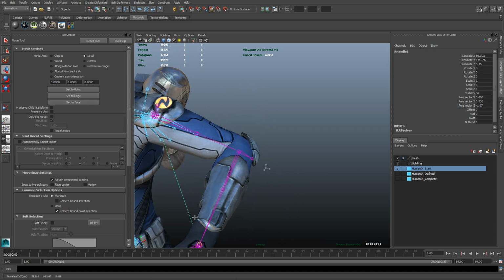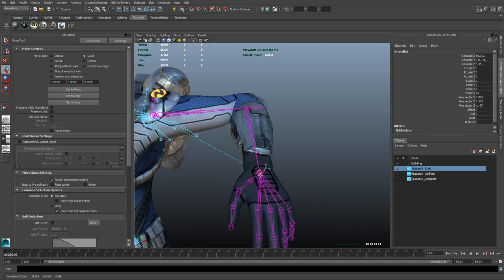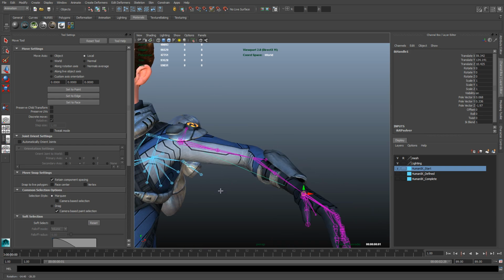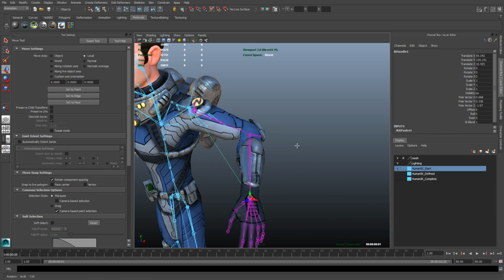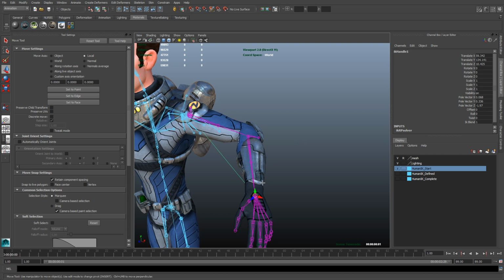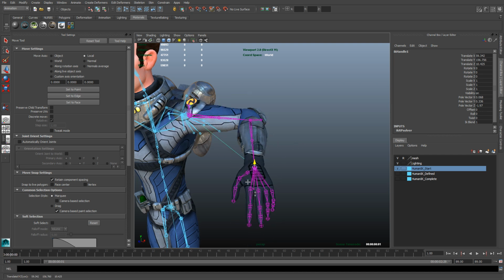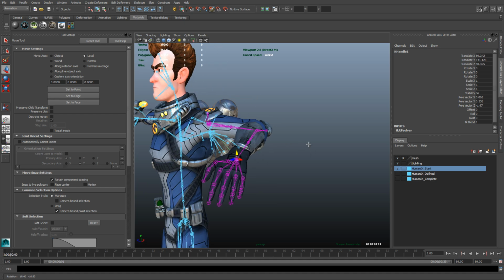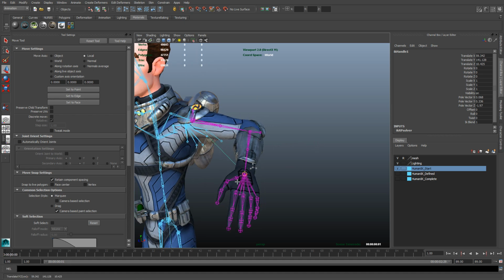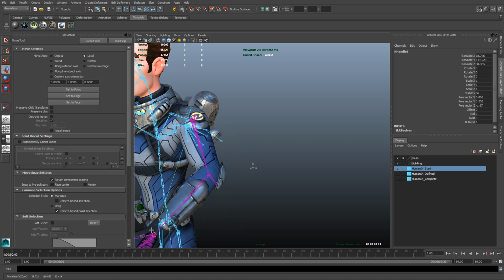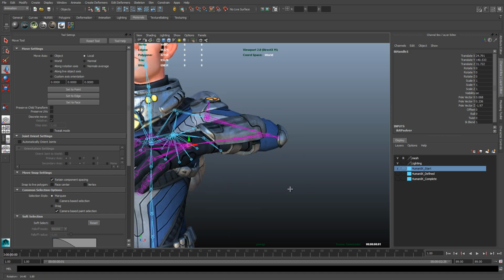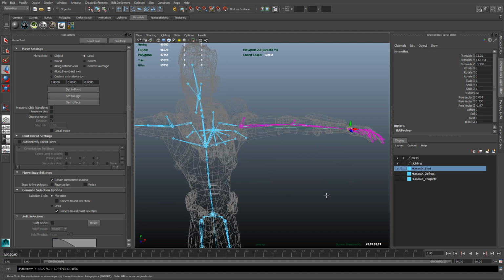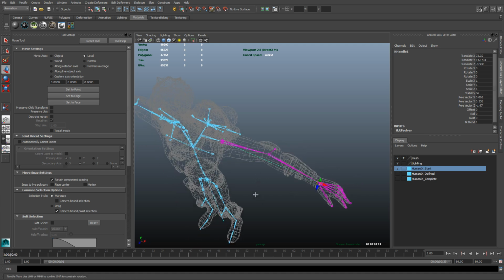And we can see very nicely how easy it is to animate the entire arm just by moving the wrist around. Alright, so that's basically how to set up IK. Now, sometimes when you set up an IK solver, it doesn't provide as much control as you'd like it to have. Specifically, in this case, the elbow might need more control. There might be a position where we move our arm to that creates a very unnatural location for the elbow to be. And this is where constraints can help to provide more control to your rigs.